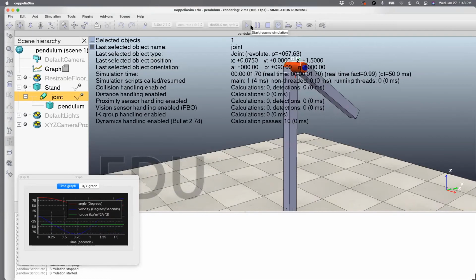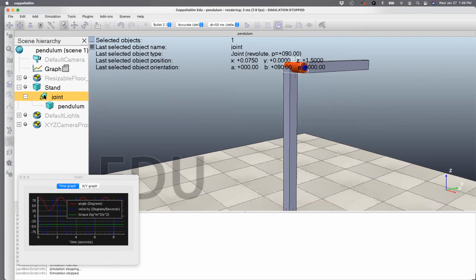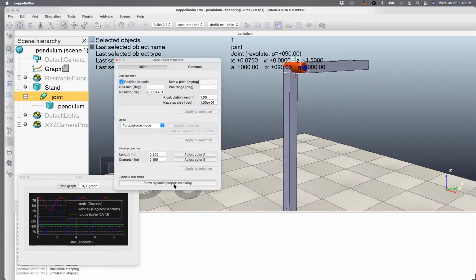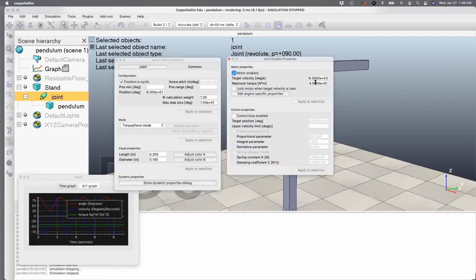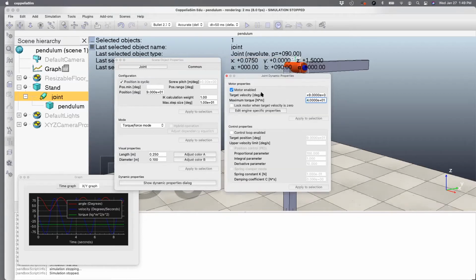You can see it sag down. It's trying to put in a little bit more, and that's why it goes back and forth. But I hope you get the idea that that's how you set it to do torque control. That is, you max out the velocity and then you put exactly the right torque.